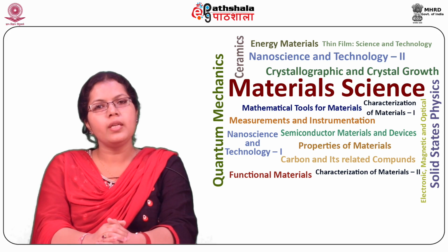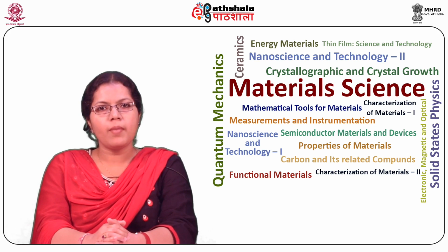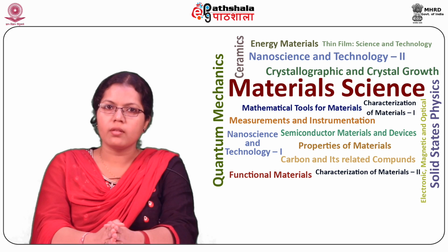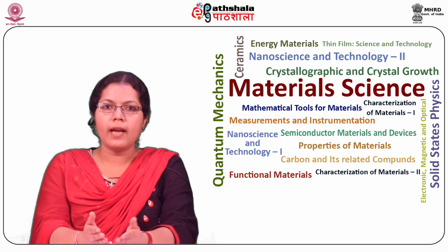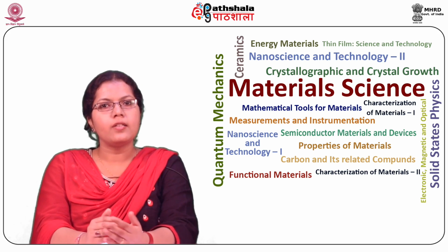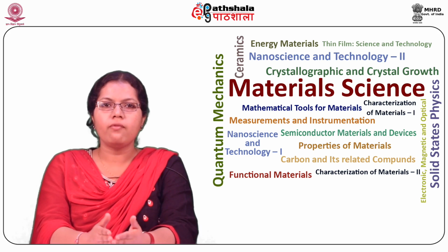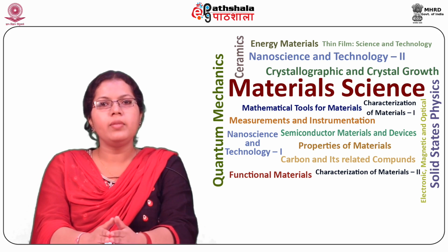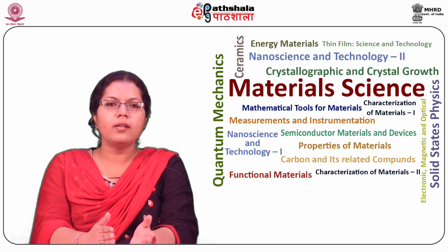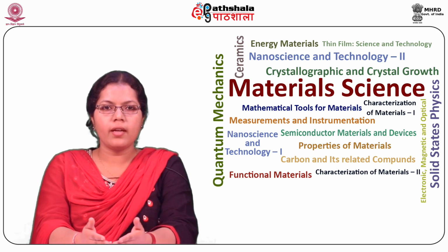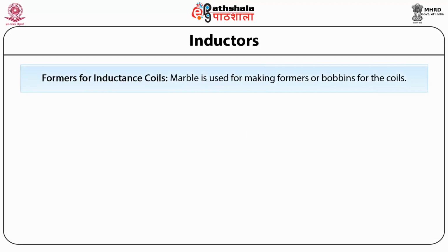The inductor should be so designed that capacitive effects are negligible. This is particularly important for inductors working at higher frequencies, where the interturn capacitance may drastically change the effective value of inductance. The inductor should desirably be unaffected by external magnetic fields and should produce a minimum interfering field of its own. Formers of inductance coils.